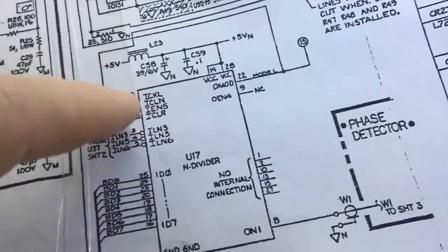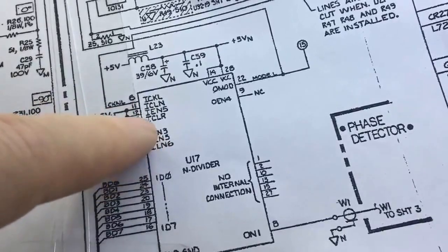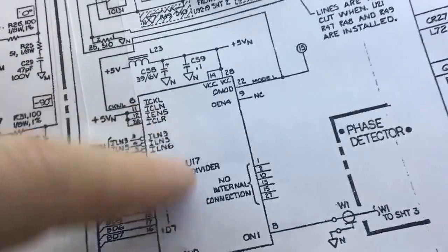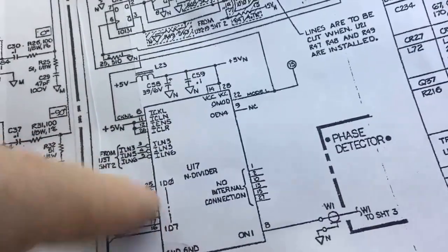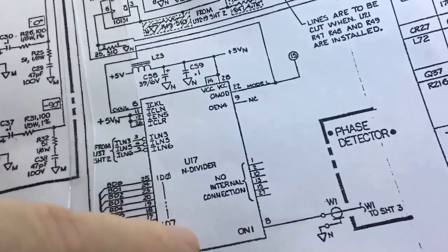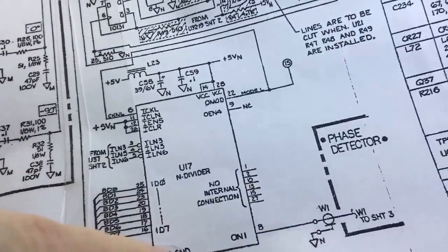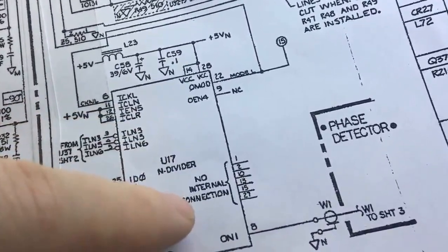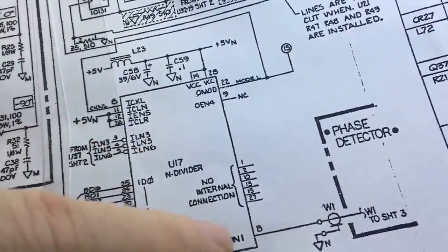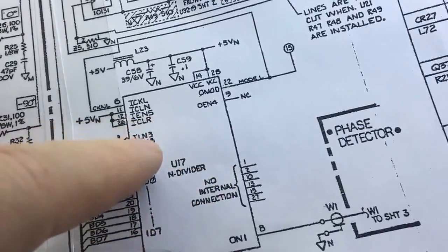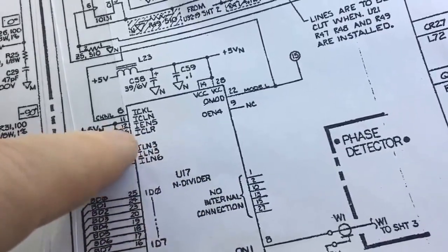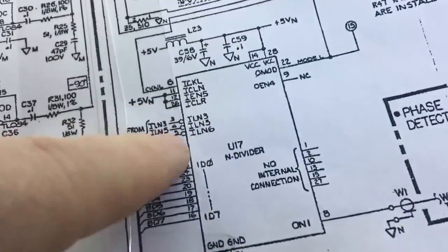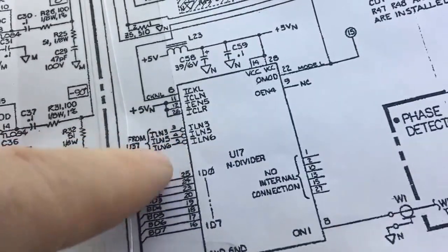Arduino's what I know, there's probably other stuff which is better for it, but to actually replace this chip, I could take that signal in, divide it down based on this data coming in here, and spit a signal out, using PWM or something. Maybe PWM, maybe digital addition, you know, binary addition on the outputs. That's also possible.